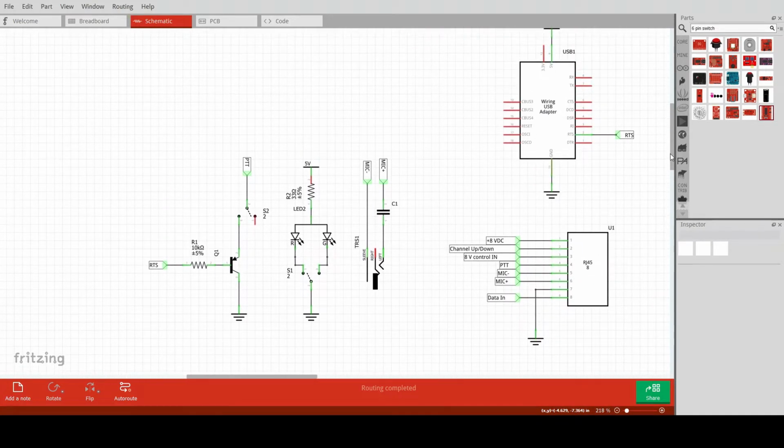Now, as I talked about when I measured the microphone plus signal, I noticed that it had that DC offset. And so I knew for sure I was going to need some type of isolation capacitor. I looked it up, and there's lots of debates on how big, what size should you use, and I decided that a 10 microfarad would be the best. I knew I wasn't going to create a filter that I would lose too much of the audio that I needed with that size, but I would do the DC decoupling and not allow voltage to go into my PC and damage it.